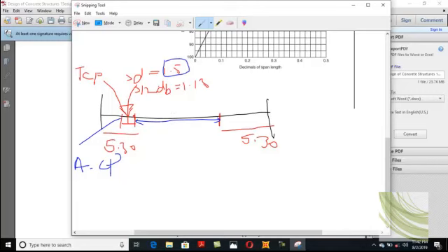But now you also need to extend this bar to this side also for a distance of 1.50, because you have to extend in both ways. So now this is the actual continued length of all your bars. They must be continued for a distance of this much.